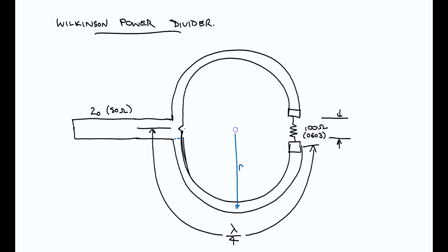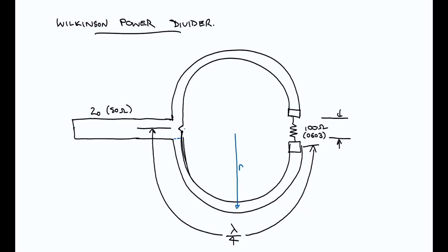And so when you're designing this, you want to start with the very center and find the radius of your arcs. They're almost 180 degrees, and for a quarter wavelength, the arc length, S say, is 2 pi r times the angle on 360, right? So that simplifies because the angle is almost 180 degrees anyway. So let's just be rough here and simplify it. Now, of course, there's plenty of calculators and spreadsheet tools, and you can work it out based on the actual size and gap from the resistor footprint.